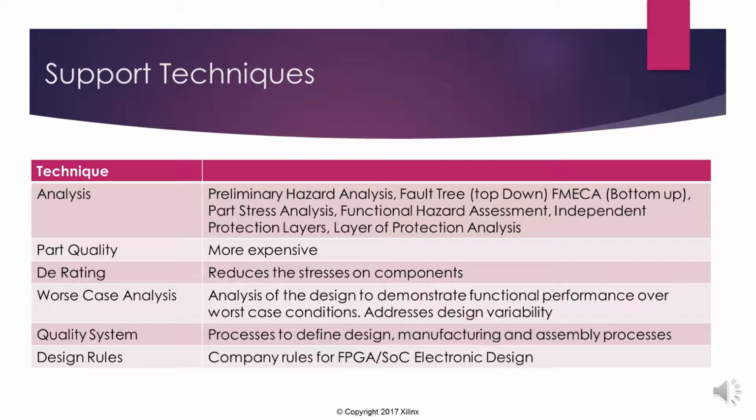We can do derating, which falls into our part stress analysis, so we can apply electrical and thermal derating stresses to our components to ensure that they're not all being run at the maximum, to reduce the stresses on those components, increasing reliability. And we can do worst case analysis.